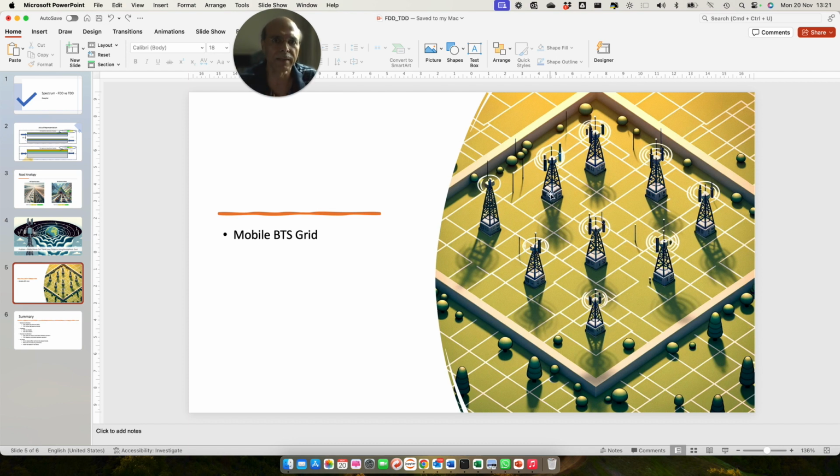Everybody will be transmitting for 20 milliseconds, and then as soon as the transmission is over, they will be in the receiving mode. Now the problem is that as soon as it is in receiving mode, let's assume that the signal from this base station is getting transmitted and it is continuously in the air. It does not die off. It does not attenuate. It keeps traveling and it comes to this particular base station also. It reaches this base station. Now this distance can be as high as 20 kilometers, 30 kilometers, 40 kilometers, right?